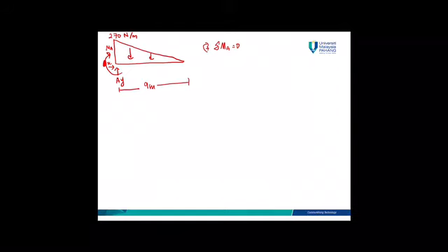You need to calculate the area under the graph. 1/2 times the magnitude 270 times the distance is 9. This one will be your force. You know that moment is equal to force times distance, and the distance is 1/3 times 9.